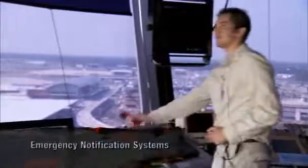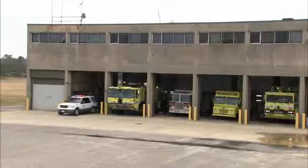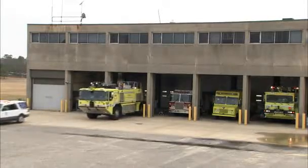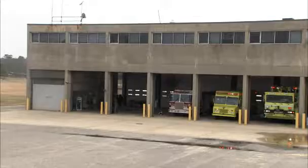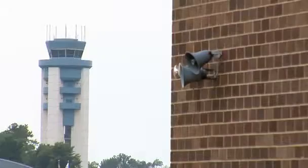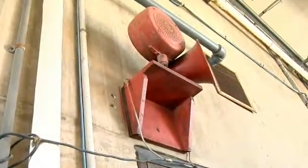The air traffic control tower will often have a direct phone line to the airport fire department. ARFF personnel may also receive emergency notifications from flight service stations, air carriers, 911 calls, or airport staff. Klaxon horns, rotating beacons, and other alarm devices may activate automatically when triggered by emergency alerts. Alarm systems should be tested daily and should have a backup power source.